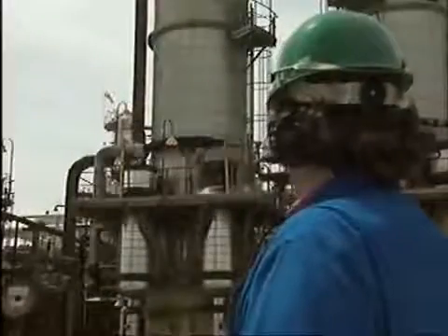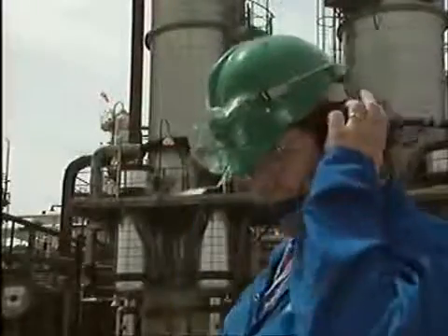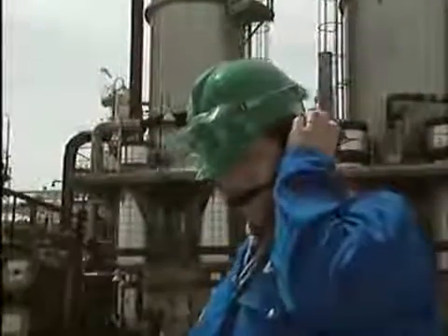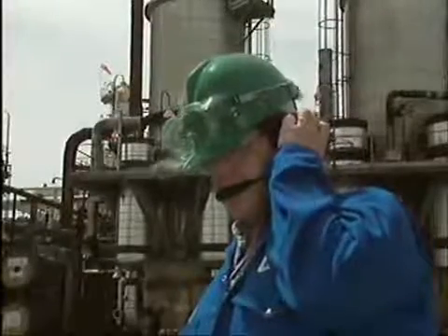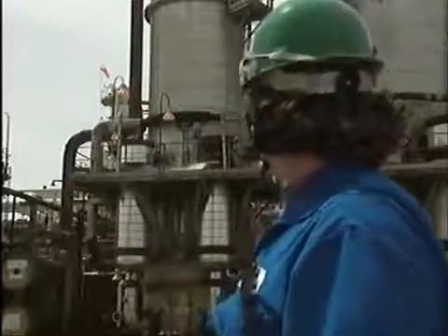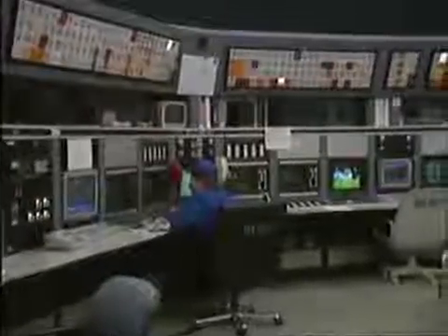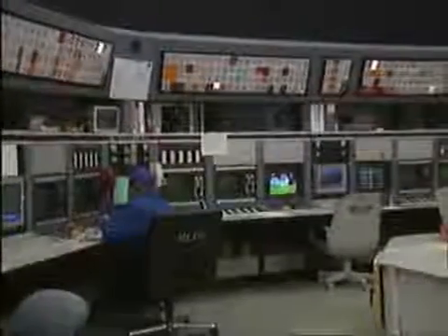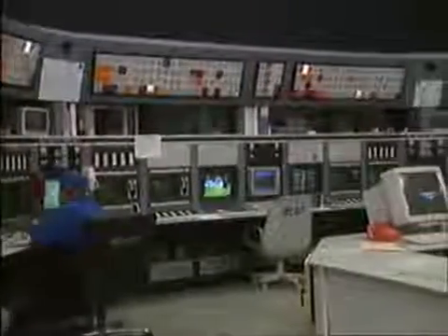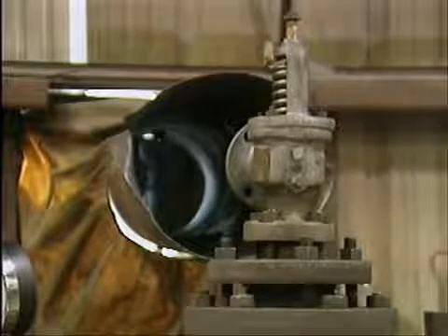properly. But any time a safety valve is lifted, there's a corresponding drop in system pressure. So before you hand lift a valve, notify the appropriate operating personnel so that they can compensate for the drop in system pressure and keep it from interfering with normal operations. If operating personnel aren't forewarned, when pressure drops as you hand lift the valve, they might take emergency measures to raise pressure or to shut down the system. Such actions could be costly and perhaps dangerous. Likewise, before hand lifting a valve, you must take appropriate personal safety precautions.